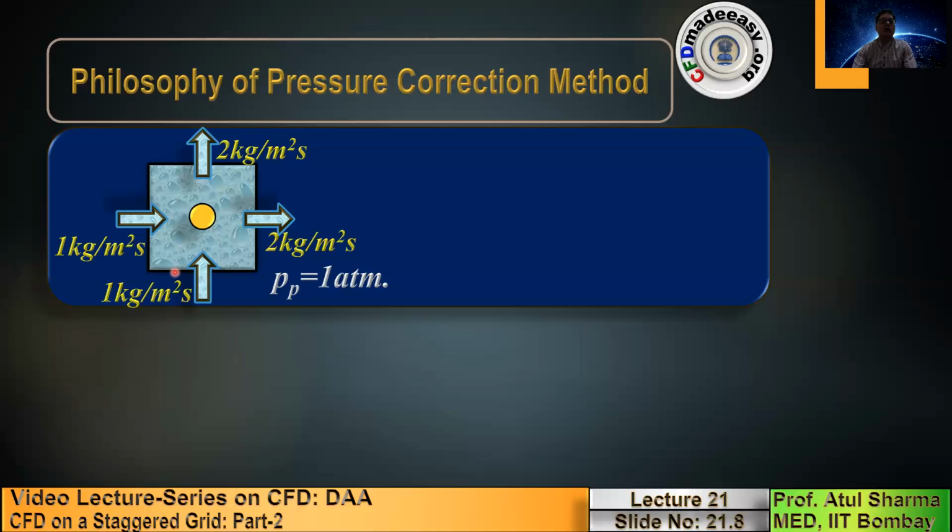So when you have more mass going outside the surface of the control volume, the idea is based on whether the net mass outflux is positive or negative. Let us suppose you are given the freedom to tune the pressure inside this control volume, like a radio knob, you can control the pressure inside it. Let us suppose right now this pressure corresponds to 1 atmosphere. So if more mass is going out, would you increase the pressure or decrease the pressure?